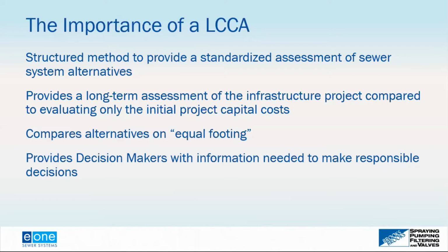So the importance of a life cycle cost analysis is you want a structured method that provides a standardized assessment of sewer system alternatives. If you have engineers working in different offices or communities that have to submit information to a regulatory or a funding agency, you want everything to be done in a standard method so that when someone looks at it, they know how it compares to another assessment or even the other alternative within the assessment they're currently looking at. And it provides a long-term assessment of the infrastructure project compared to only evaluating the initial project capital cost. This allows the stakeholders to really compare the alternatives on equal footing.